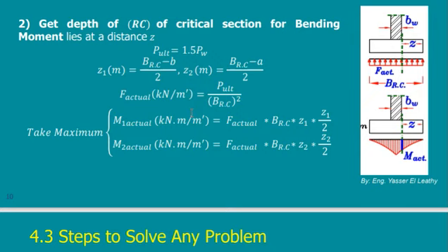Now I stop using the geotechnical code and go to the reinforced concrete code. I know the dimensions, I know the area. Once I know the area, I can design the rest of the footing, which is the depth of the footing and the amount of reinforcement.